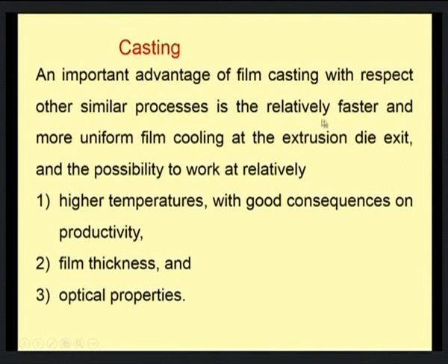Now, if you look into the advantages of film casting, particularly with respect to polymers compared to other methods, the method is relatively fast. This is a continuous process, therefore the method is fast, and then more uniform film cooling at the extrusion die exit is possible, and then the possibility to work at relatively higher temperatures.